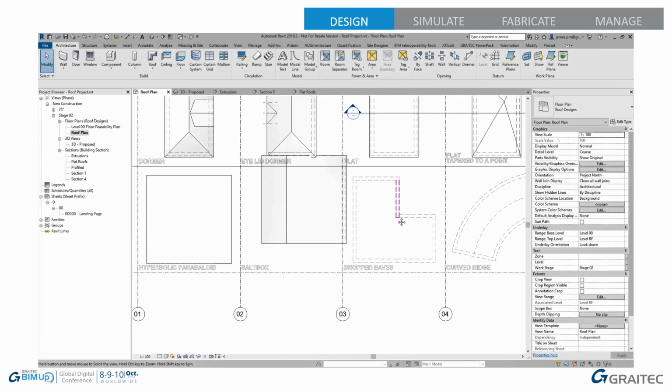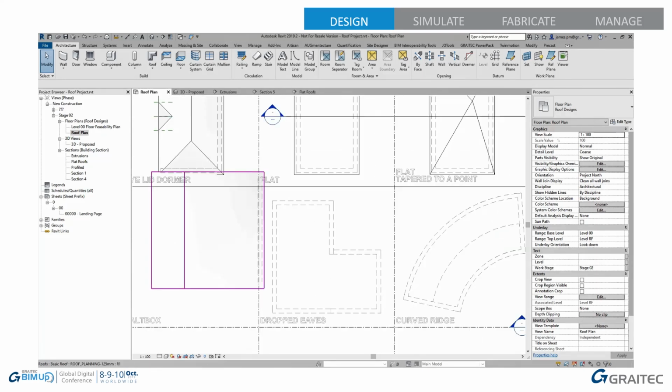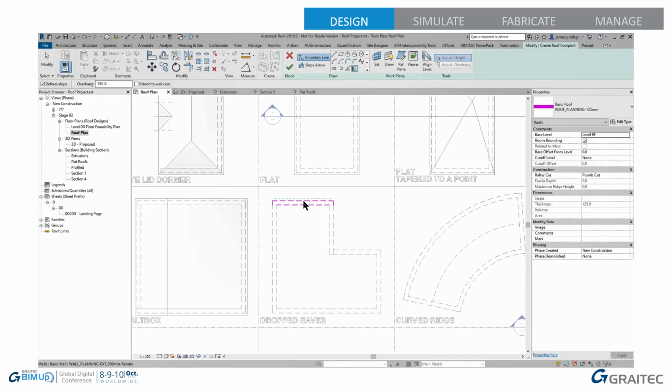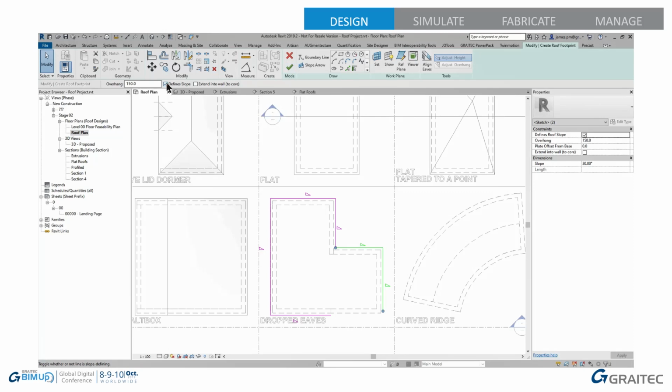Okay, so let's have a look at this next roof. Oh, I must have just moved the saltbox accidentally. Let's just undo to move that back. There we go. So a dropped eave. It's a little bit like where you've got a roof over the garage that continues the slope down. This time I'm going to show you a little bit of trial and error, because you're bound to make mistakes when you do it. I know I did when I first learned how to do this. So I've created a partial roof, and then I'm just going to create another area of the roof here. Oh, I keep picking the wrong button. There you go. That's what happens when you're trying to do things fast. So I'm going to take the slope definition off of these lines here.